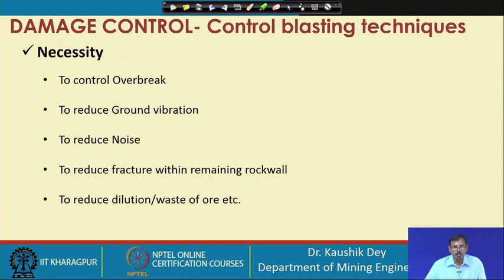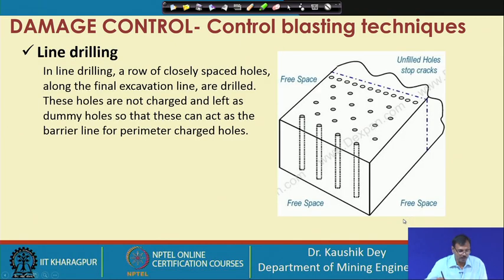Similarly, on the surface also, it is often required that the sidewall slopes be monitored or retained for a longer life. In those cases, all damage towards the wall must be controlled significantly, and that is why damage control is a very important requirement while blasting is carried out as the excavation technique.